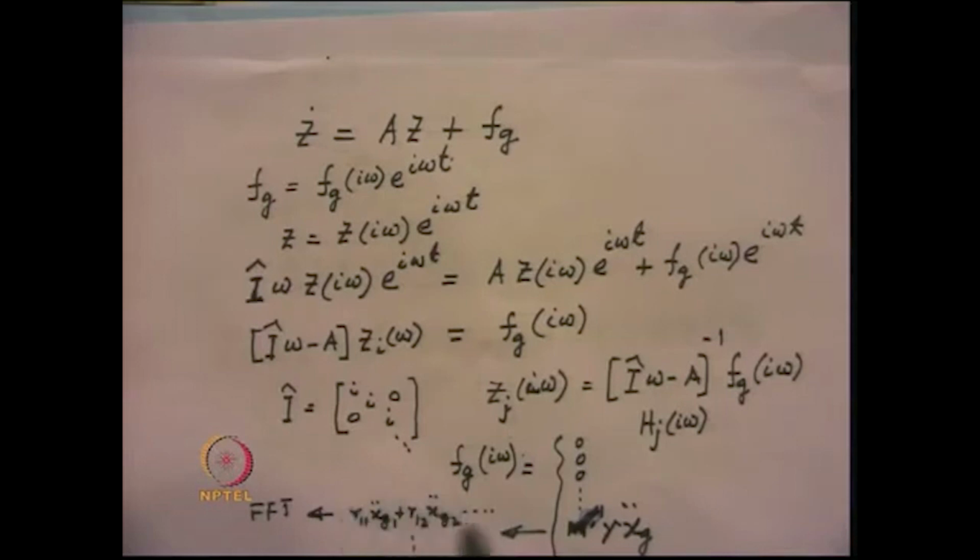That will be the one element, and in time one can compute this and can get a particular value in time, and that is how we can have all the values of the elements at every instant of time t that we feed in the FFT. So, we have to now carry out FFT for the n number of time histories, because corresponding to all n degrees of freedom we will have one excitation.